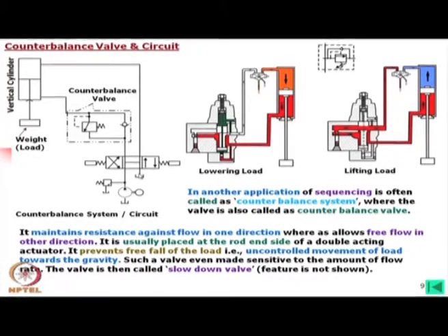Again, we do not need a very fast response here. We can slowly lift the load and lower the load. The main purpose is to handle this load, not very fast operations. So we can go for open center to save energy, right. Now, let us think of lowering the load, because that is the main purpose. While we are lowering the load, we allow this to go to tank, that means we will go to the left hand side.